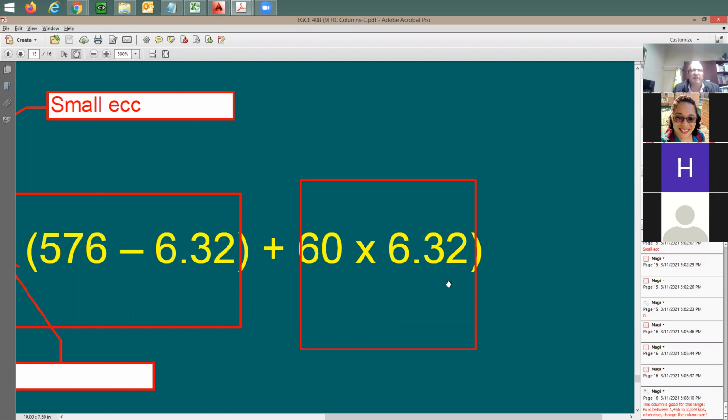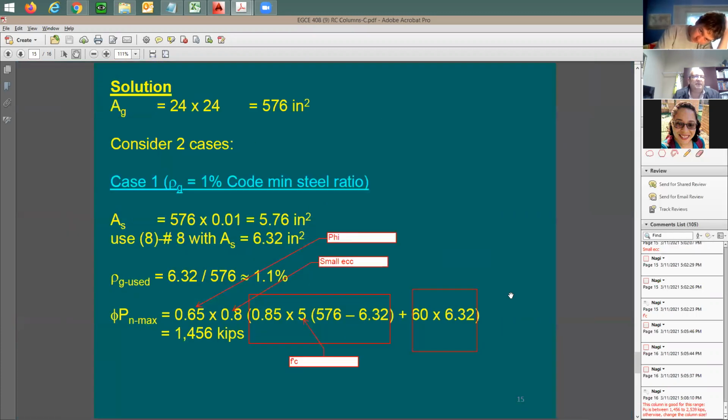And usually the amount of steel that you put there is not gonna be like this amount of steel. You don't add number 8 in compression, right? It's gonna be maybe a couple of rebars, for example, 2 number 5 is gonna be 0.62 versus 6 square inches. So it's gonna be maybe 1/10 of that, so you can just ignore it. I see. Okay.